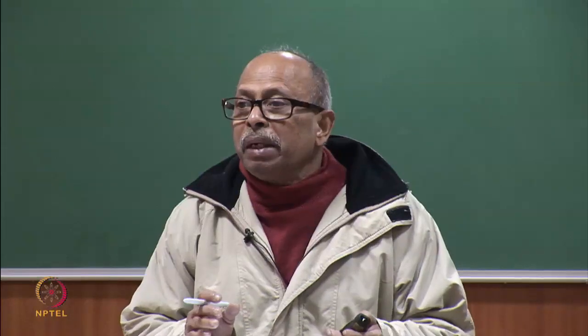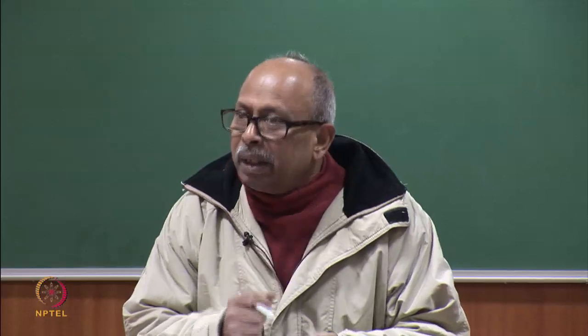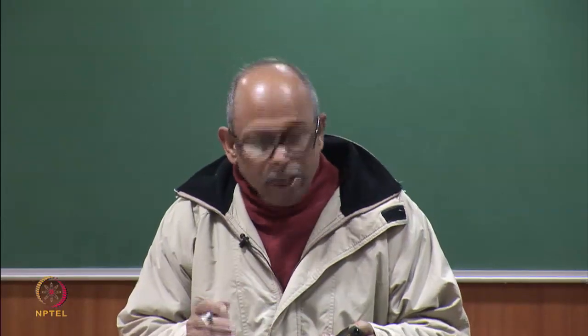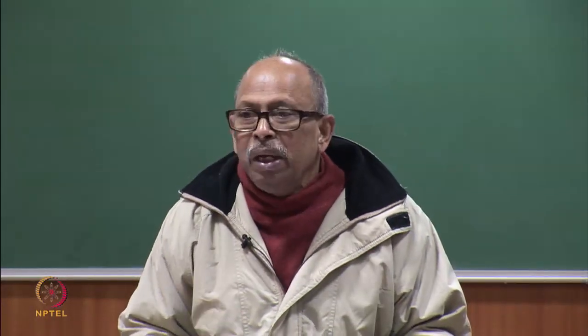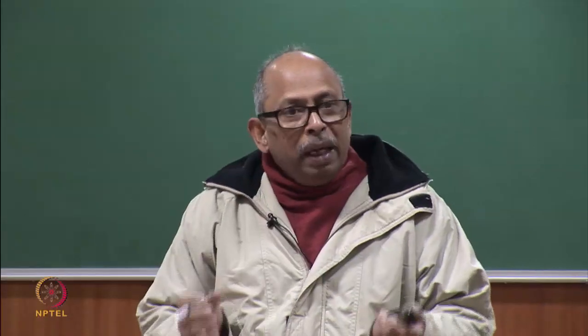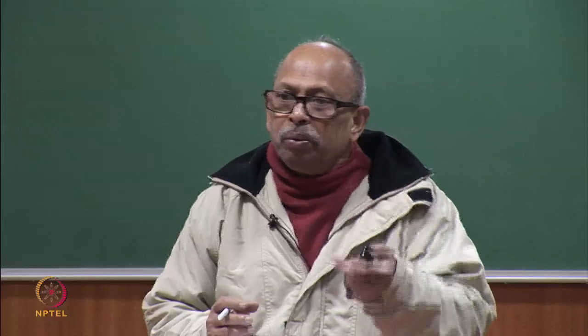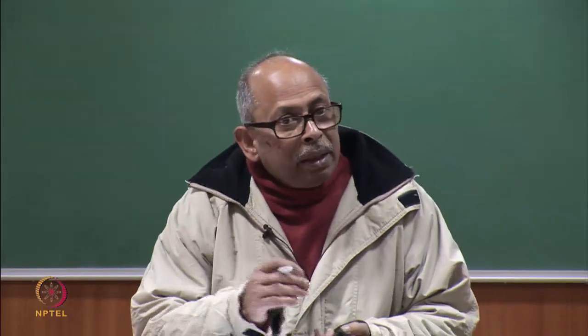So, some stress might even get relieved. 20% stress you have given, then heated it up, there will be some stress relief. So, therefore, you might find that this is actually taking higher load, because you have already pre-compressed it, then you have heated it up and then tested it from 20% to whatever failure. So, there is a nullifying effect.